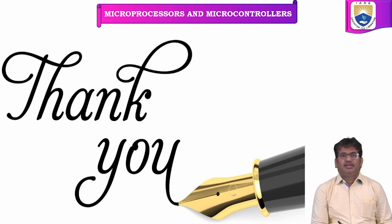So with this, I conclude. Today we have discussed the 8255, which we call PPI, Programmable Peripheral Interface, or PIO, Programmable Input Output Device. This is for interfacing an IO device with the 8086 processor. We studied the various features of 8255, then the various modes of operation, that is BSR mode and IO mode.